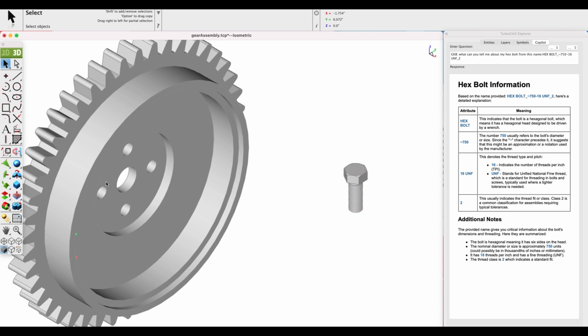One more thing that's kind of a useful tip when working with the fastener library is how to insert them into a part. To do that, we're going to pull out the advanced transform palette, and we will pick the assembly tool palette, and then from there we will do insert face.